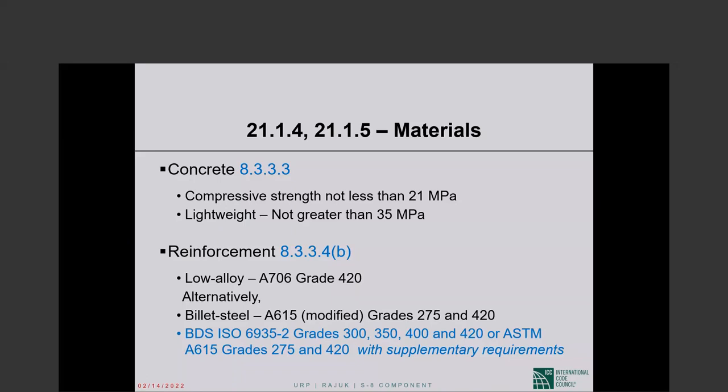And that upper limit, as I mentioned, is because we do not have sufficient test results demonstrating that the hysteretic load deflection behavior of lightweight concrete members is comparable to those of very similar normal weight concrete members. As more test results become available, that limit may very well be relaxed, although the limit has held now for quite some time.